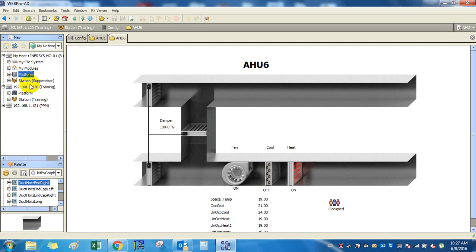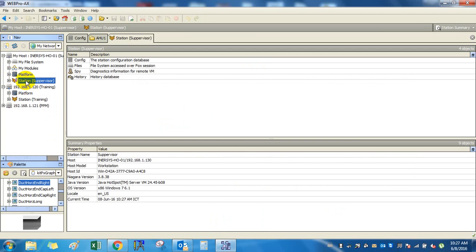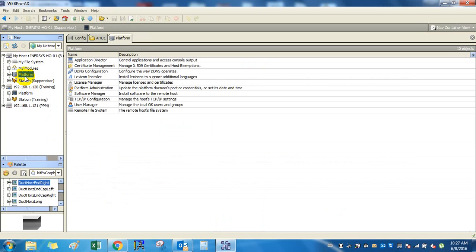So when you relativize, you reuse the same file again and again. No need to create 10 different files for 10 different AHUs. Okay? Becomes easy to change, becomes easy to maintain. Yes. Question, for the copy of 5 AHUs, if we want to modify some graphic.